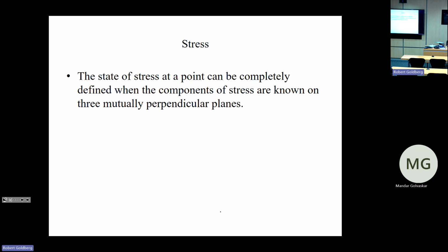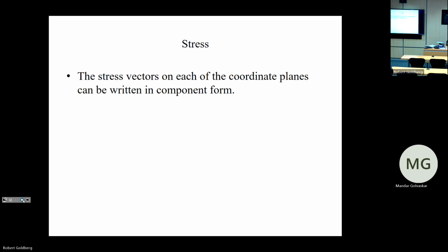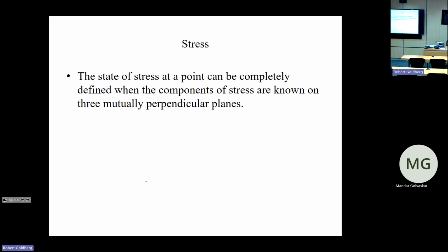So what we can say is, we can say the state of stress at a point can be completely defined when the components of stress are known on 3 mutually perpendicular planes. So we have our point, we have our x direction, and the y direction, and the z direction.